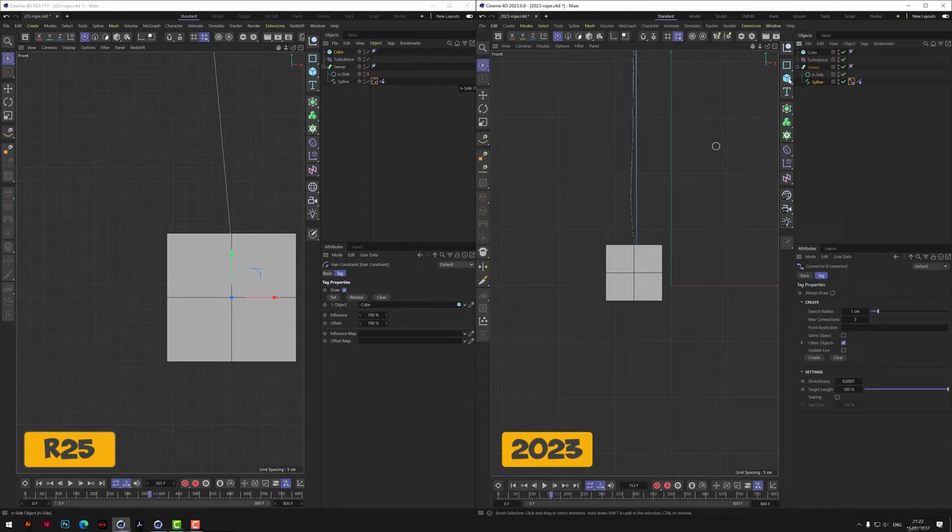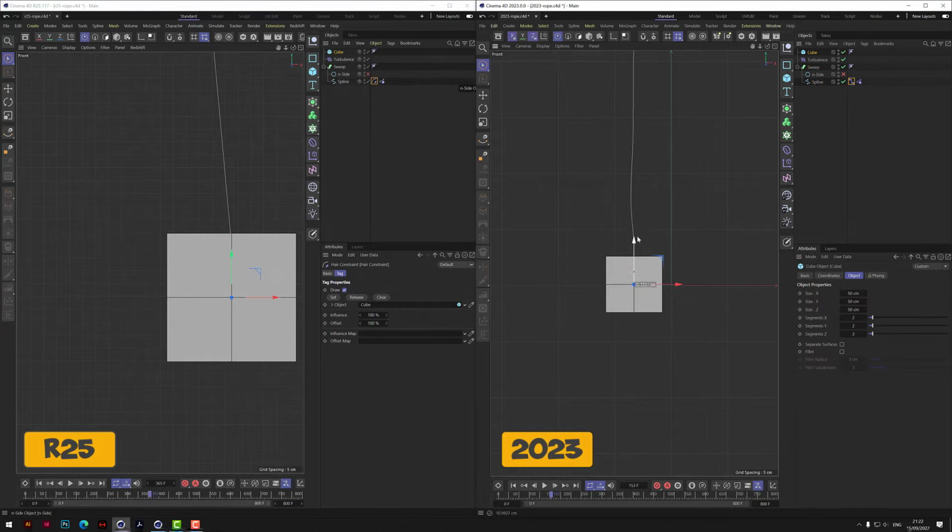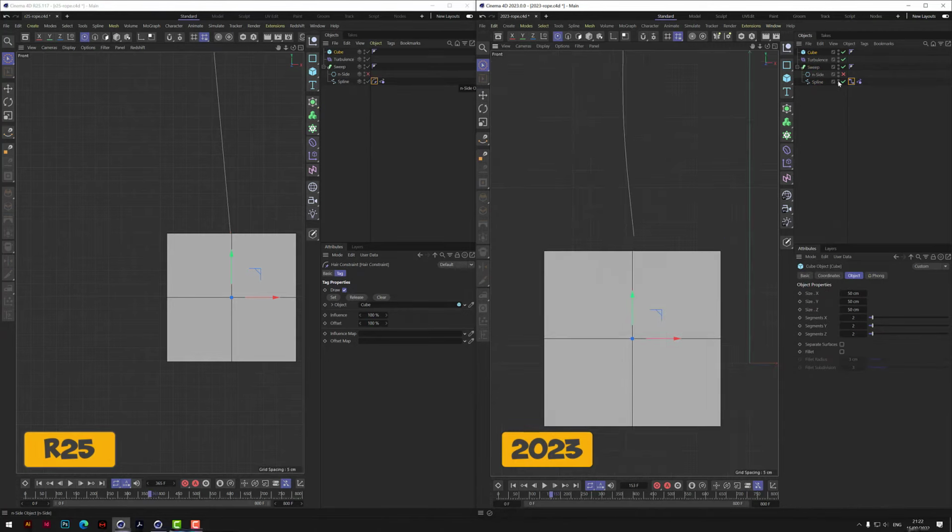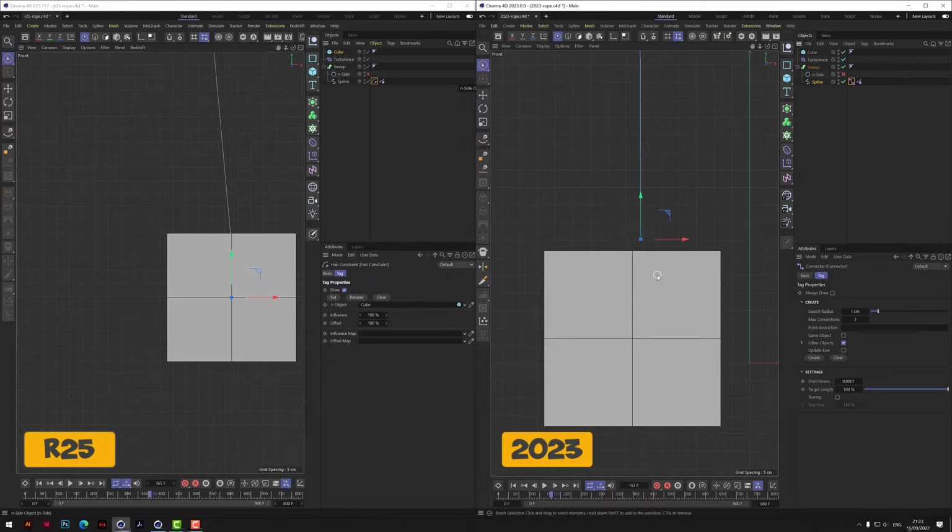So with the connector, let's turn off end side so you can just see the spline. Let's do the same thing. Let's just move that box down a little so we can see the end of that. Right, so what we do then is we click on the end point, onto connector, and now this is a slightly different menu. This is going to look for a point with the search radius.